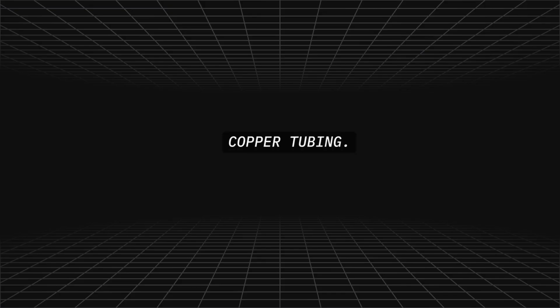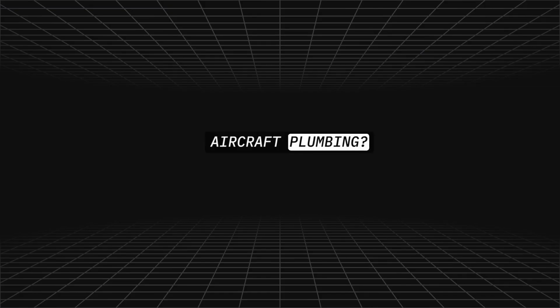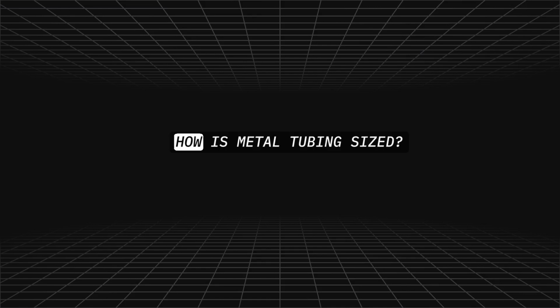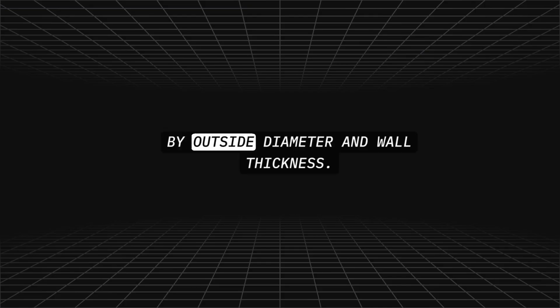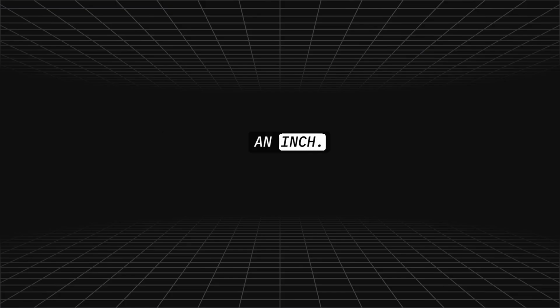Copper tubing. What are 2 types of commonly used fluid lines used in aircraft plumbing? Metal tubing or flexible hose and fittings. How is metal tubing sized? By outside diameter and wall thickness. Outside diameter is measured fractionally in 1/16 of an inch.